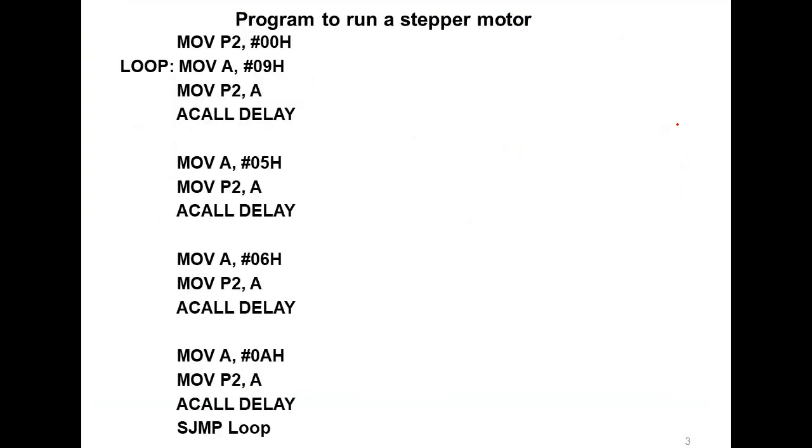So here this is our program. Port 2 has been chosen as output port because the stepper motor is an output device. So obviously it has to be made as output port. So the 00 we are sending is to make port 2 as output port.